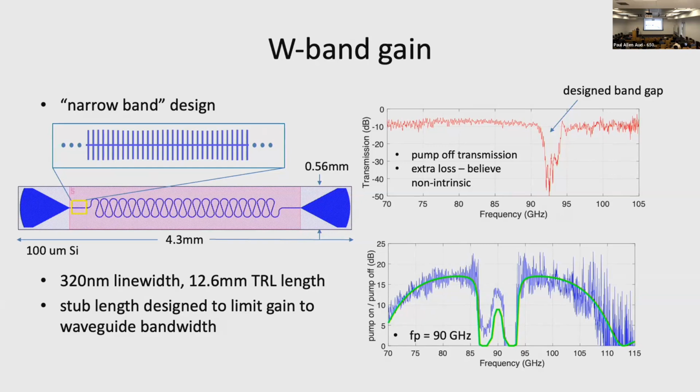You can compare this critical current in this formula with what you would compute from the plasma frequency of the film, which is an intensive parameter, and also the characteristic impedance, and see by how much those critical currents differ. That would give you a sort of intrinsic strength of the nonlinearity that you could compare with the dissipation. So that maps this kind of film onto an array of Josephson junctions.